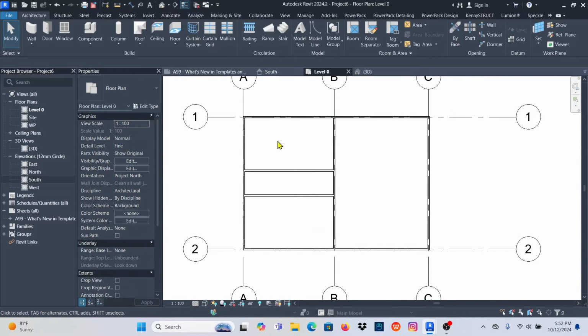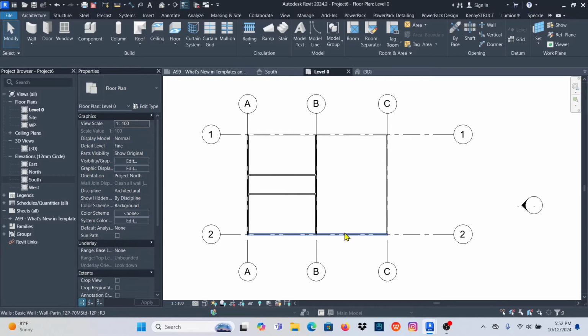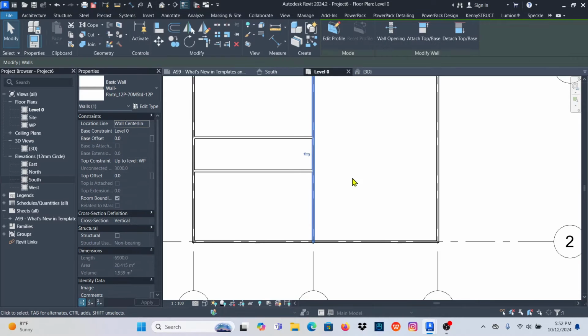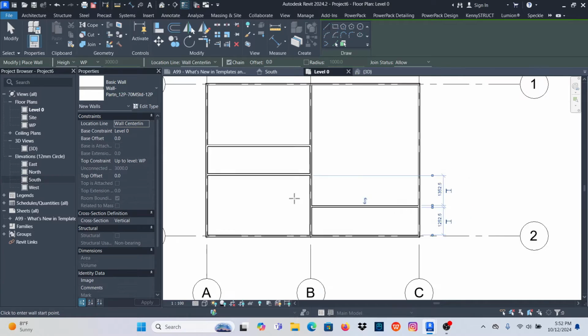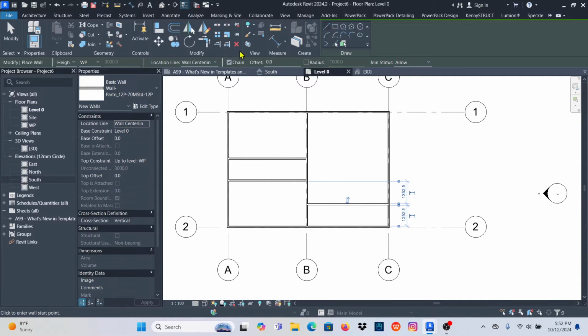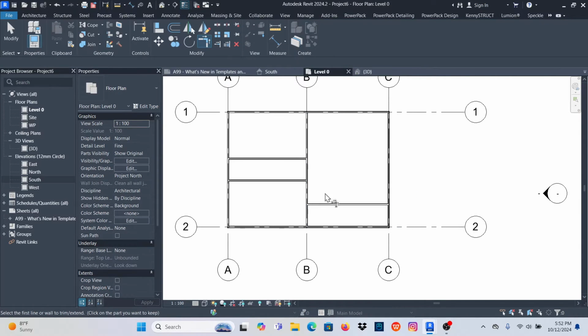Now let's proceed to the creation of our doors, and before that, maybe let's make a few modifications here. If I just select the wall, I can right click and create another wall. If I just want to have about 1.3 there as a porch, I'm now modifying according to my design. I'm in the wall command, and I have the tools to trim what I want. TR on your keyboard, you can just go to Trim right there. Then I can just click that one and that one. I just want to trim the corners so that my design can be like this.